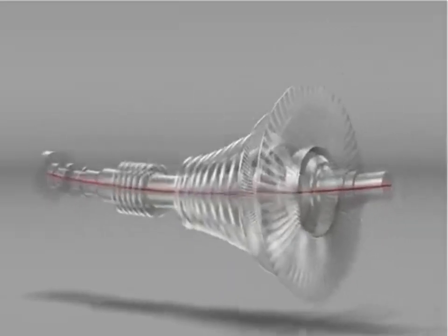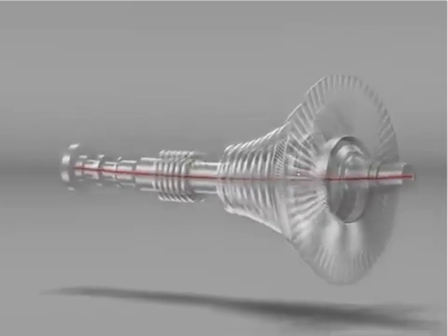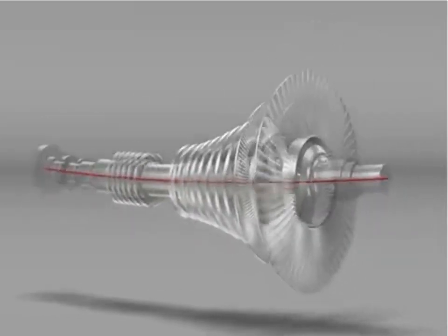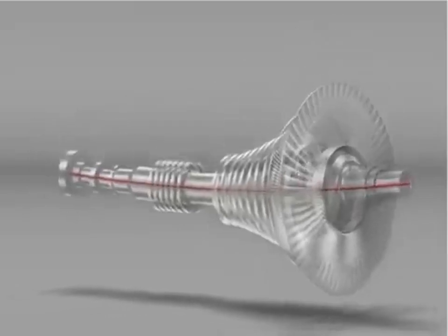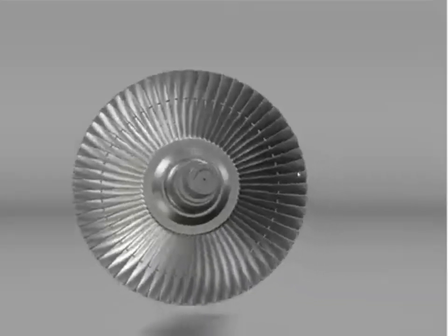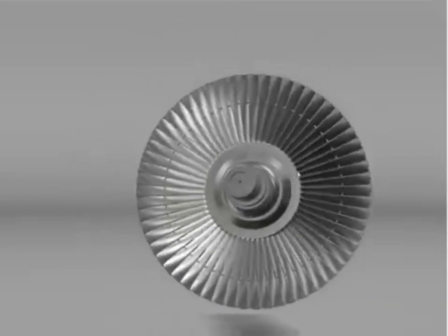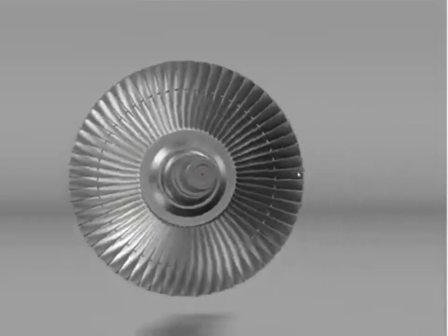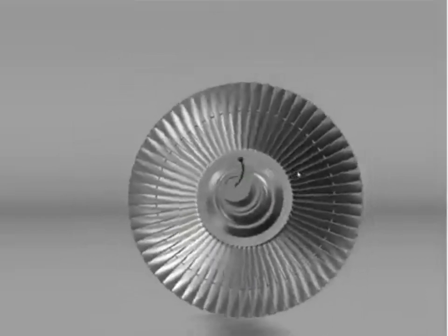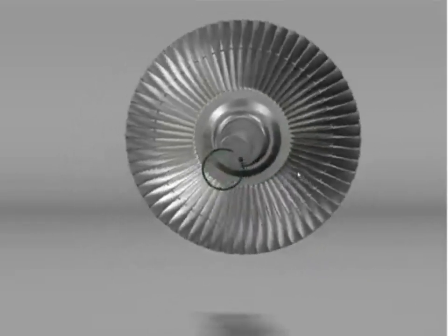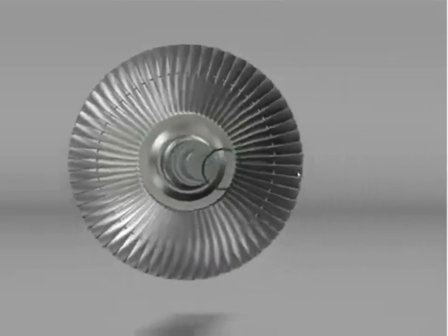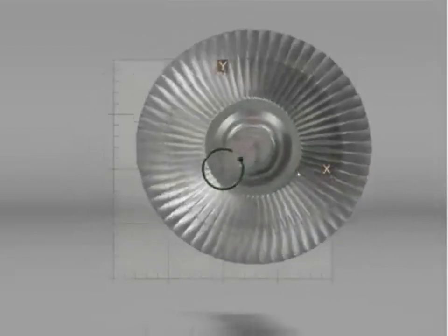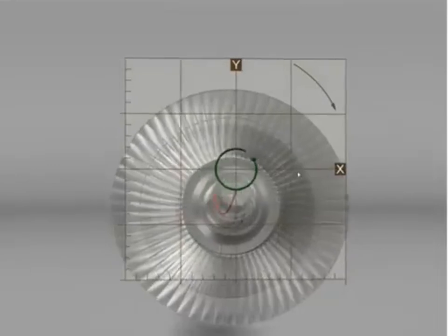When the machine goes through its first critical and maybe second critical speed, it will actually flex. Not quite as much as what we're seeing here, but our orbit measurements tell us what's going on. So basically, if this was a very exaggerated end view of that rotor, we are very interested to know what the center of the shaft is doing. And so we can see it now. It's drawn out this orbital motion. And that's actually what those two proximity probes give us.